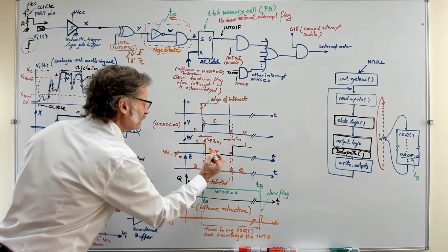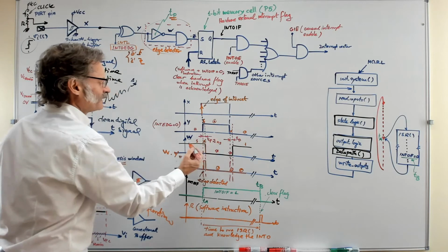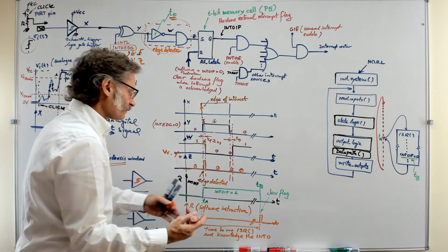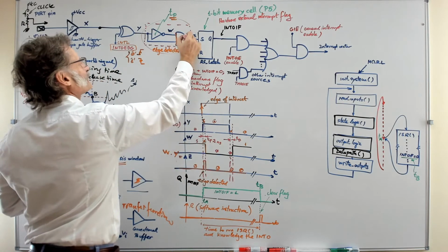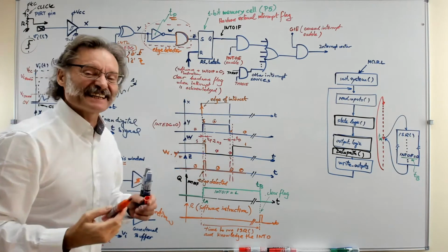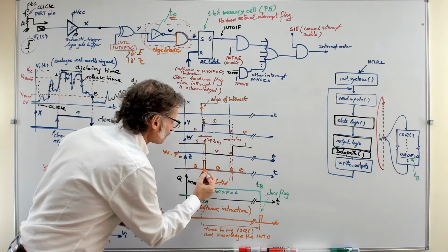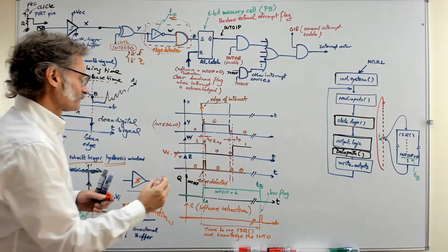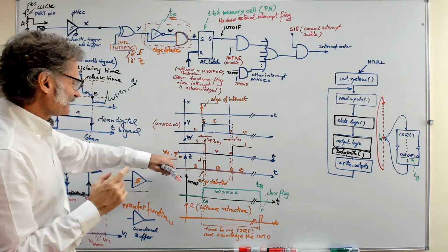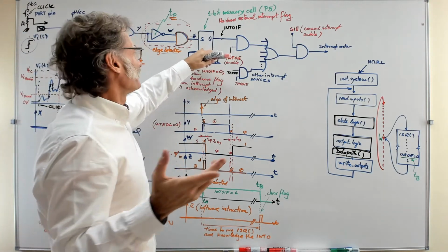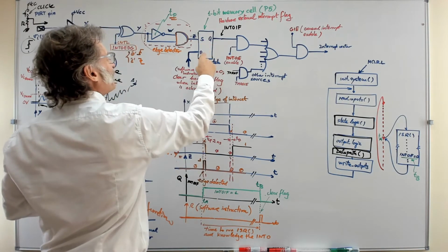Look at this. You have a 1 and Y is still a 1. Well, Y is a 1 and W has not yet toggled to be 0. So you have a 1 and a 1, and this AND gate, which is very fast, as you can imagine here in this ideal circuit, can detect that thing and generate a teeny pulse. But you know, a teeny pulse, you see, that is just the set input of, for example, to make it simpler, an RS latch.